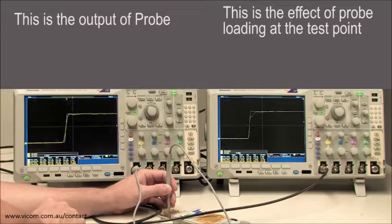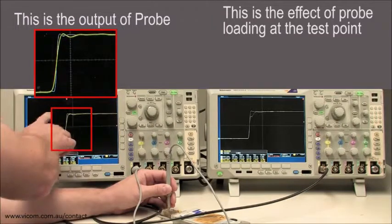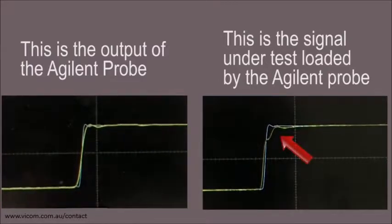Here's the output of the probe, and the signal looks as you might expect. The waveform shape of this signal is similar to the original signal, which is shown as a reference. The rise time of this signal is somewhat slow at around 800 picoseconds, and the amplitude compares favorably at around 246 millivolts.